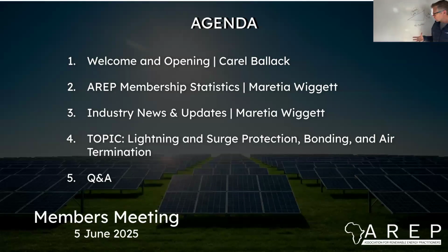When they had their solar system installed, the active or real load reduced to 5 kilowatts because of the solar that was installed, but the apparent power stayed 50 kVA, and the reactive power stayed 50 kVAR as well.